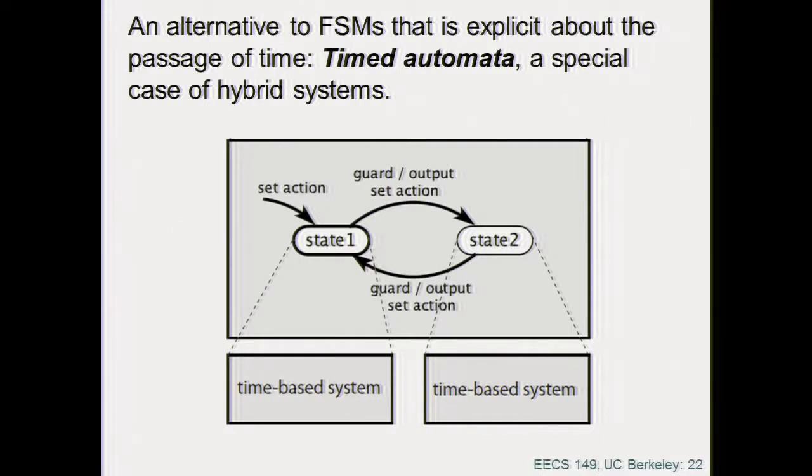Now, suppose it may very well happen that one of the generators blows up, right? Very possible. So what happens? Oh my God, half of the plane goes down. No. What happens is that the buses can be crossed. So this poor generator that had to do only the left part gets to do the right part as well.